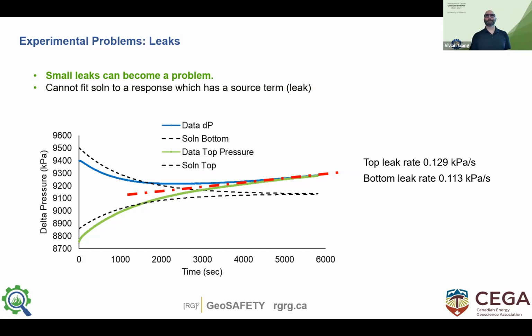Sample size. If you're planning on getting rid of that porous stone, how would you make sure that you're actually getting the distribution? Right, that's the question. What more can we do to reduce the storage volume or the upstream and downstream volumes in the reservoir to get a good response out of the system without compromising the entire test? There are all of these other issues, like, are we channeling up the side? We're assuming a uniform pressure front through the specimen, which you kind of have to do. Very interesting. Great presentation.